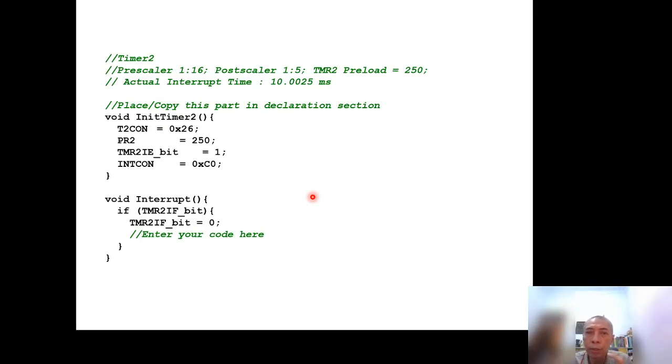So you can make many combinations with these timers, using the prescaler and choosing the clock source and frequency according to your requirements, especially for delay time, because we use these timers for the advantage of accurate delay time, or you can measure time.